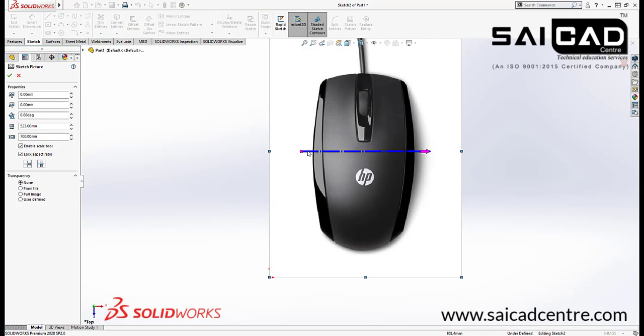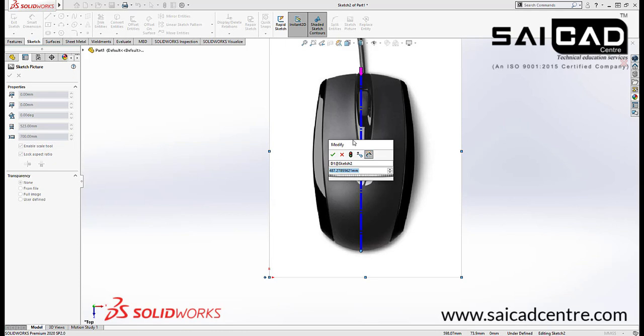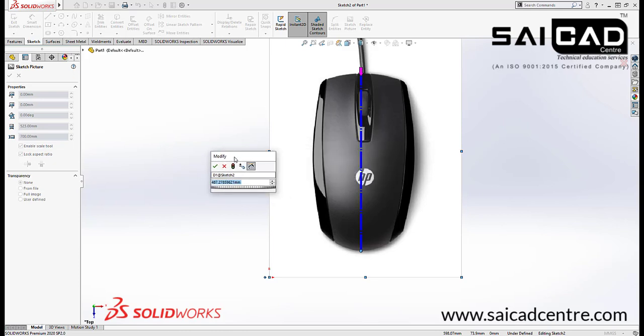Now you can see we have a scale option here, a scale tool. I know the length of this object, so I can just drag this, and now you will get the modification tool and you can define its length. The units are in millimeter.